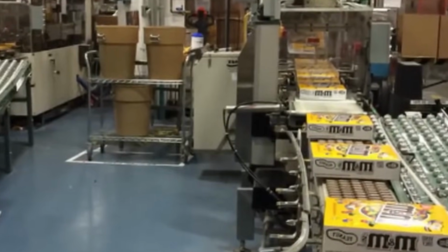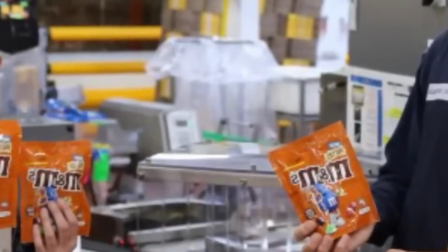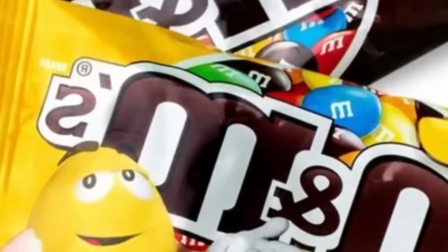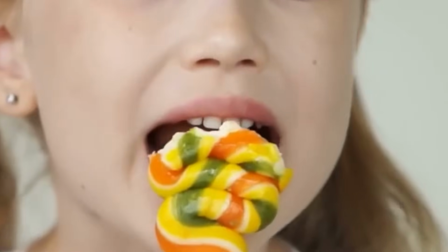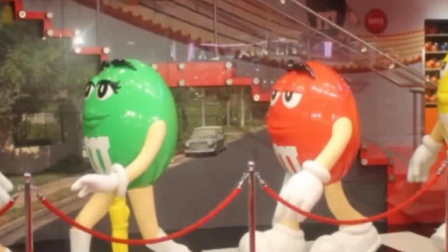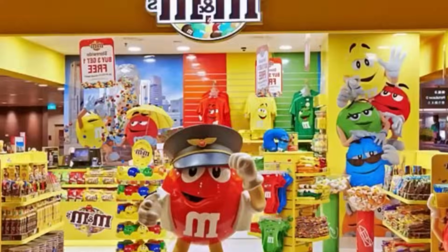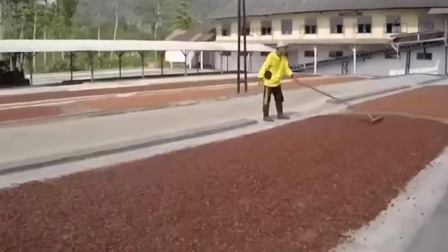Sensors within the panning unit monitor temperature, humidity, and drum load to prevent agglomeration or flattening. The total chocolate coating phase typically lasts 60 to 90 minutes, depending on desired shell thickness and line speed. By the end of this stage, each center is fully encapsulated in chocolate and cooled to under 25 degrees Celsius before proceeding to the sugar coating line.